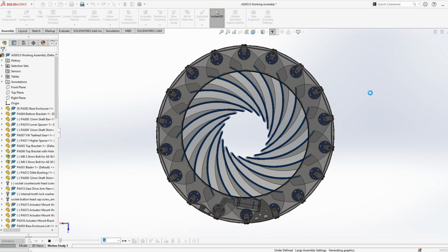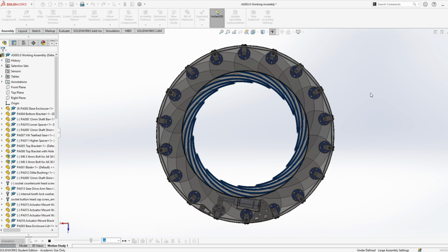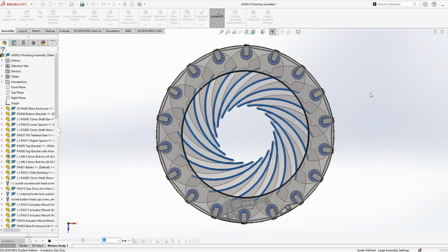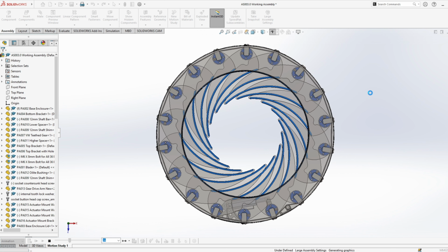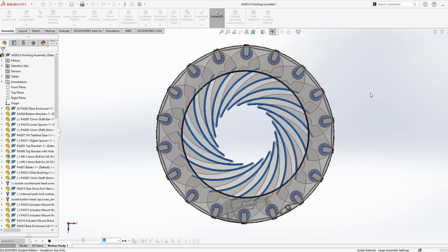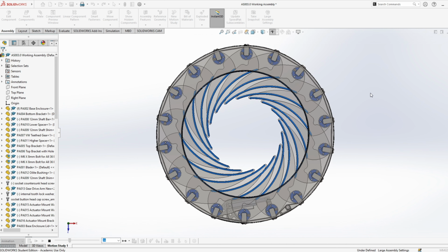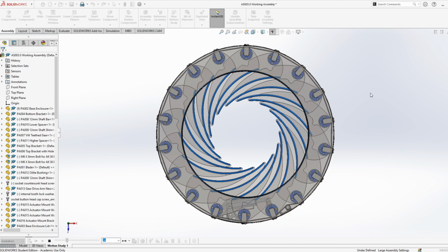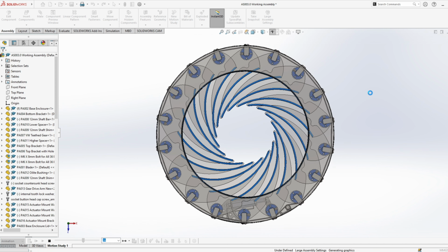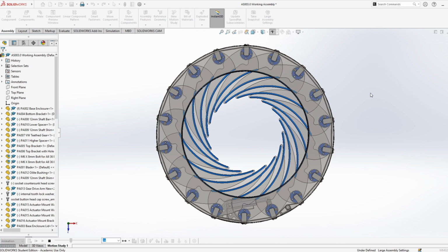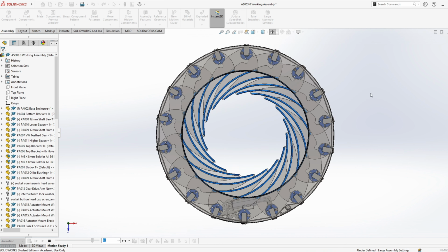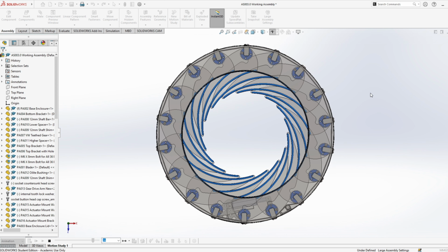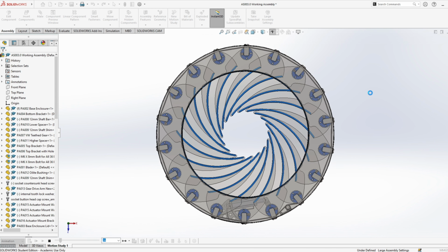So we know already that these blades within the diaphragm are manufactured from stainless steel metal, which has increased difficulties with friction when passing each other, especially at the closed and opening positions when the blades tend to overlap near the shaft mount points and at the aperture pupil of the system. So the centre of the blades and also when the blades are fully retracted into the enclosure. Hence why there's only 2 bolts at the back side of the blades to allow the adjoining blades to float or to spring where they need to spring, reducing the stresses here.